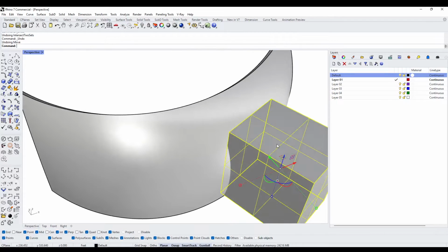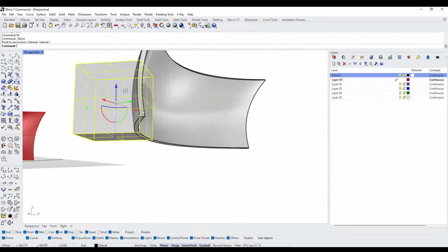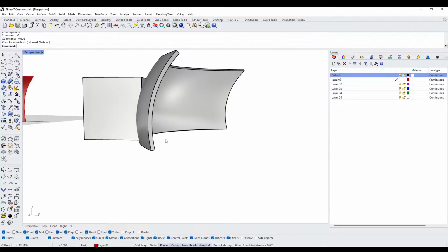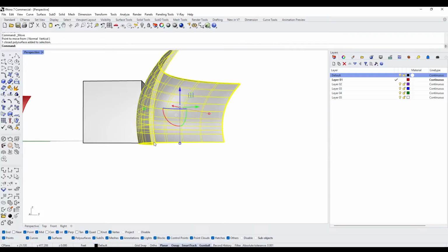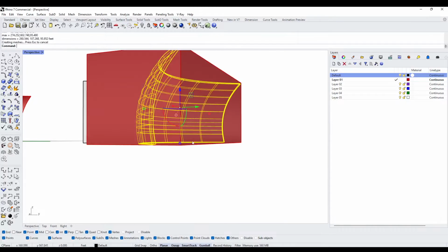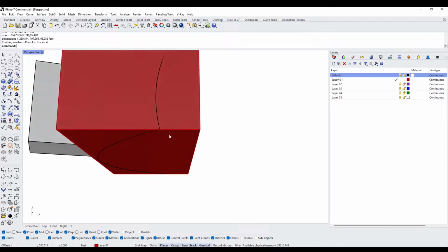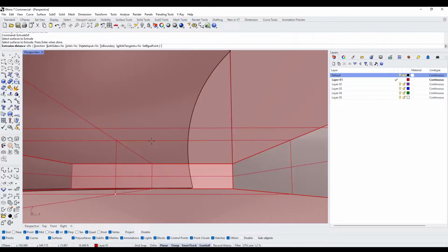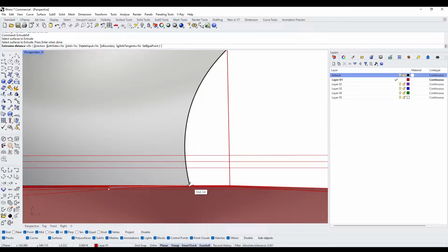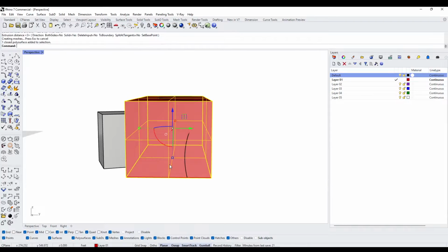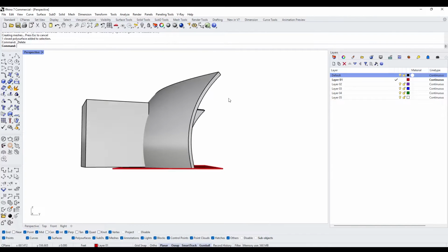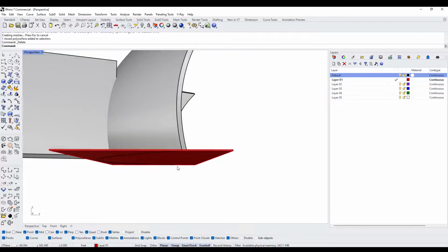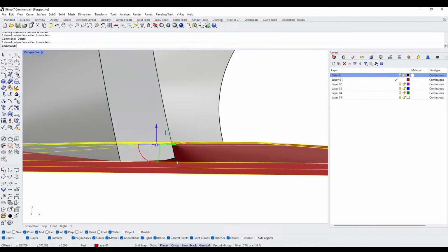So let's leave the door here. Let's say that's the location. But first we need to make sure that this is a level wall, or it's on a plane. So we'll go here to bounding box. We'll go to extrude surface and extrude this up to the second highest point. By creating a bounding box, it creates it at the exact outer boundary, taking that bottom surface and extruding it up to this location.